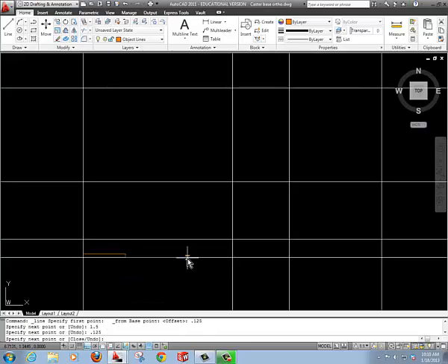We're going to go horizontal a distance of 2.5, go vertical 0.125, and then over 2.25. Vertical 0.125 to the intersection. This dimension will be 1.75, downward 0.125, over 1.75, up to the intersection, and to the intersection. If you notice, this is our front view.